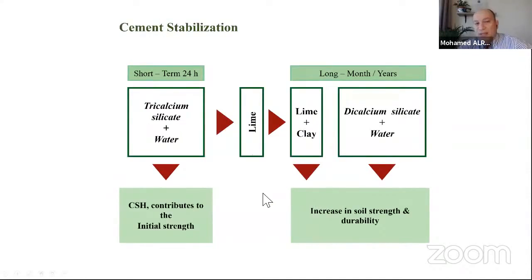For cement stabilization, the major element affecting the strength comes from this reaction. When we hydrate the tricalcium silicate by adding water, we get calcium silicate hydrate particles. And again, in the long term, there is another component inside the cement itself, the dicalcium silicate. When we hydrate it with water over a long time, we have the calcium silicate hydrate.